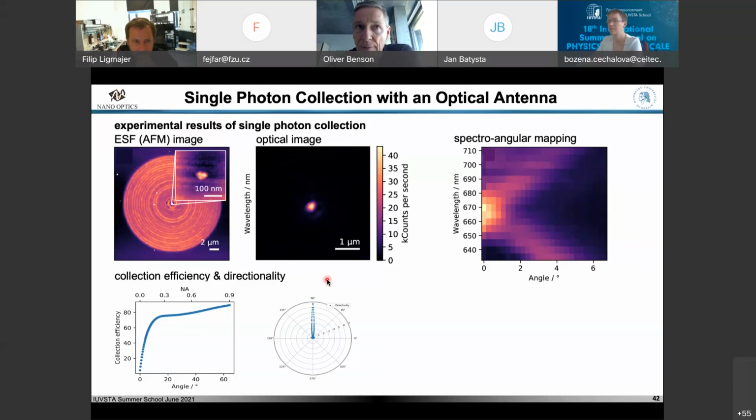That's a reasonable number, but if you plug in individual loss factors, maybe the loss through the fiber, the loss of the connectors, the loss of the photons that you cannot extract from your sample, then you easily bring this down to maybe only 1,000 photons a second. And if you think about building a communication network where you receive only 1,000 photons per second, that's not very feasible. So you want to have as many photons as possible to have a reasonable transmission rate in the end.